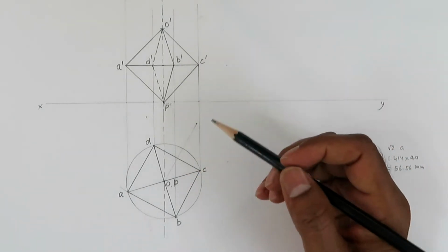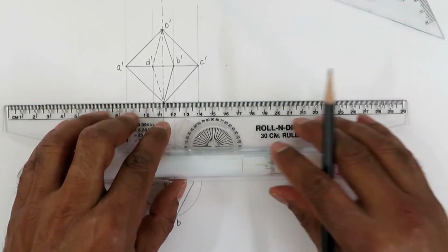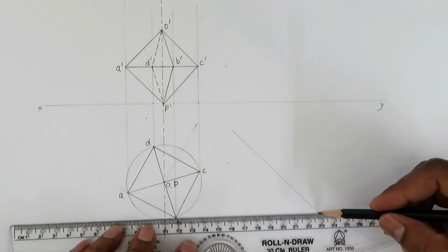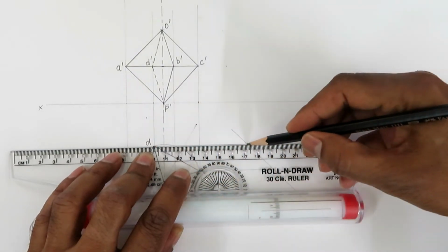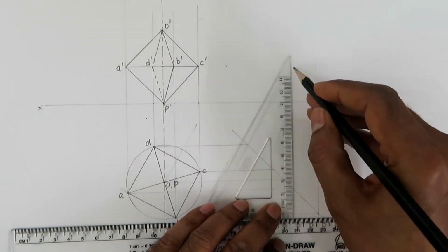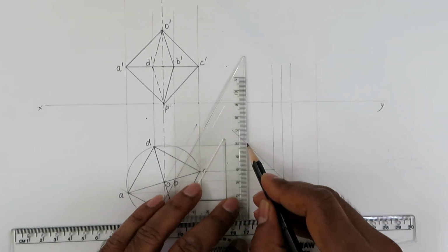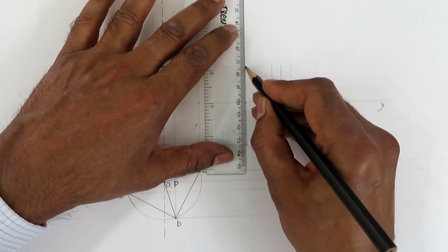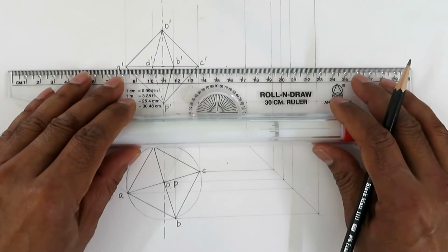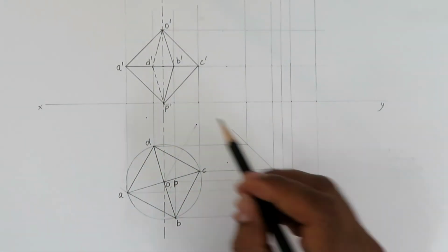So now we will make the left hand side view on the right hand side. First we will draw some construction lines. Before that we can also draw a line at 45 degrees. This is a way of projecting the dimensions from the top view to the side view. Now we should project the dimensions from the front view. So this one is already projected.